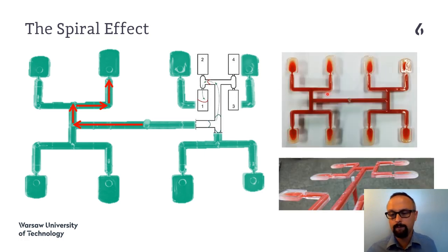It can be clearly seen here on these two pictures on the right, when we have a mixture of two materials, two polymers, which have different viscosities. To be exact, they have different thermal sensitivity of the viscosity. So the change in the viscosity is less or more dependent on temperature.